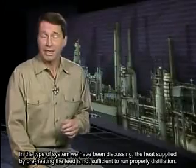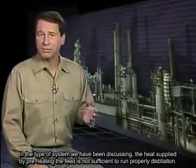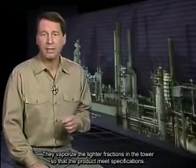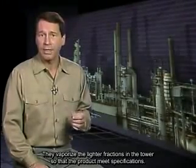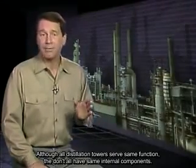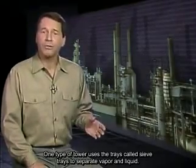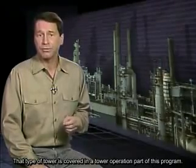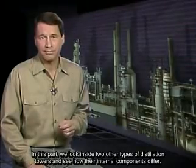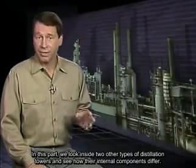In the type of system we've been discussing, the heat supplied by preheating the feed is not sufficient for proper distillation. The reboiler is needed to provide enough additional heat to vaporize the lighter fractions in the tower so that the products meet specifications. Although all distillation towers serve the same basic function, they don't all have the same internal components. One type of tower uses trays called sieve trays to separate vapors and liquid. That type of tower is covered in the tower operation part of this program. In this part, we'll look inside two other types of distillation towers and see how their internal components differ.